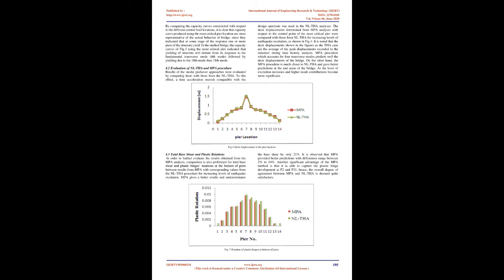For results and discussion, 4.1 Pushover curves. Applying the modal load pattern of the 4th, 18th, 19th and 31st modes in the transverse direction of the bridge, the corresponding pushover curves were derived with respect to the deck displacement shown in Figure 3. It is noted that these curves are not necessarily representative of the actual response of structural members of the bridge. For example, the capacity curve corresponding to mode 4 is rather linear, hence conveying the impression that the bridge does not enter the inelastic range when subjected to the fourth modal load pattern.